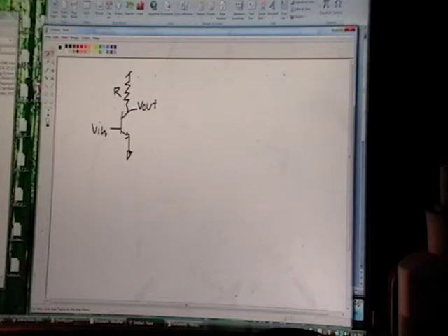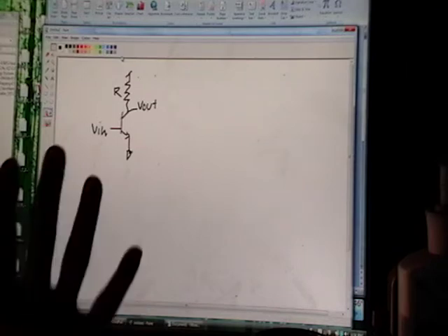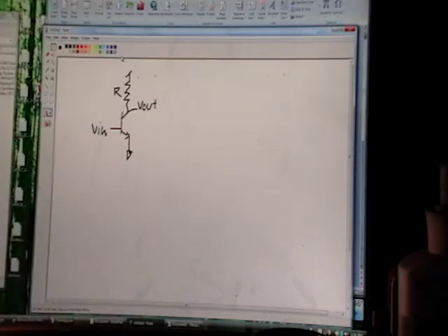Okay. So this model right here is good for working with currents and voltages. This works great, but what we're doing for the analysis for most of the rest of this class is small signal analysis, and that means we only care about the moving parts. So again, small signal, we only operate in a linear region, and that means we can use superposition to divide the circuit into two pieces. It's actually the same circuit, but two different representations of the circuit. One for DC values, which this one can help you with, and then one for AC values.